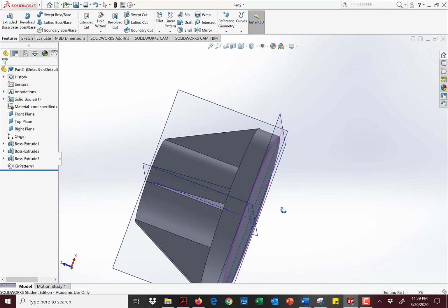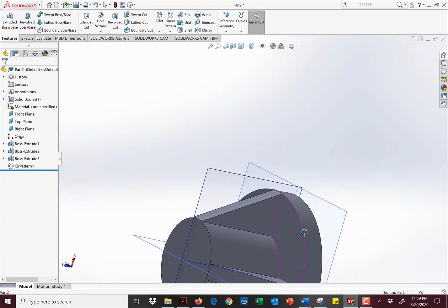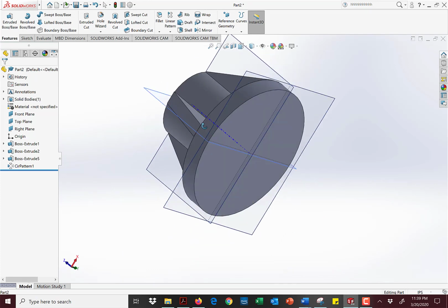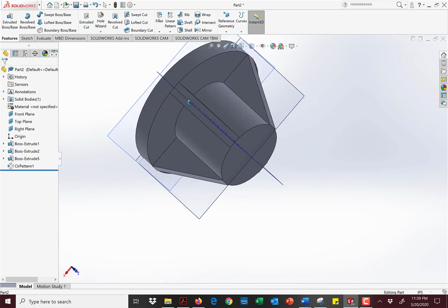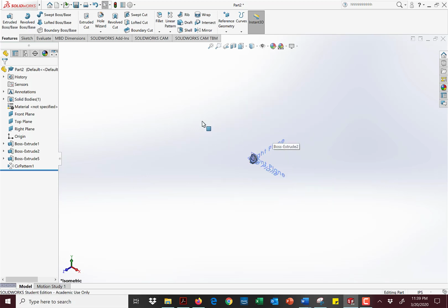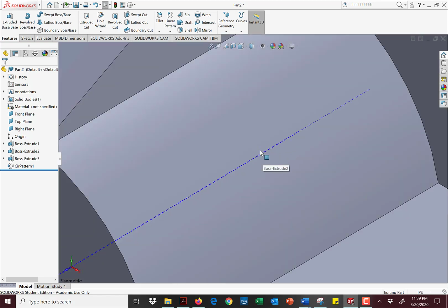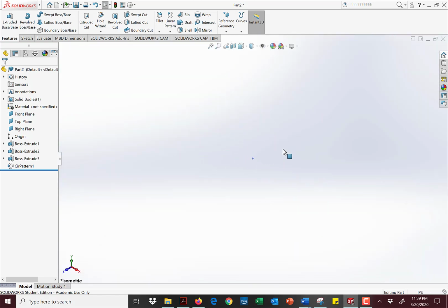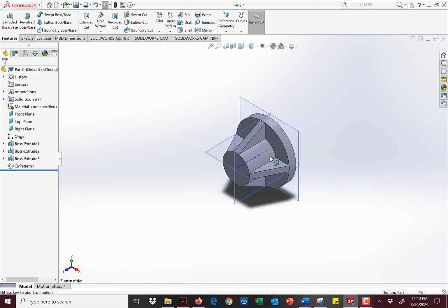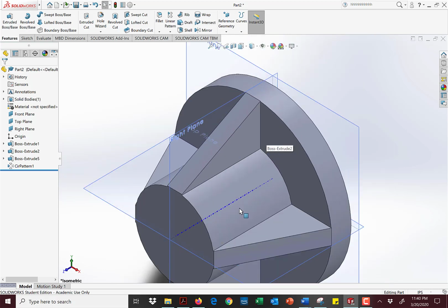The way that I'm rotating this, by the way, just so you know, is I'm holding my middle wheel. It can get a little out of hand, but boom, sorry, have to do it. So I always like to say, if you get lost where you are, just go back to isometric. If you lose your model, double click your middle wheel. It is double click. Double click your middle wheel and you'll zoom back in.